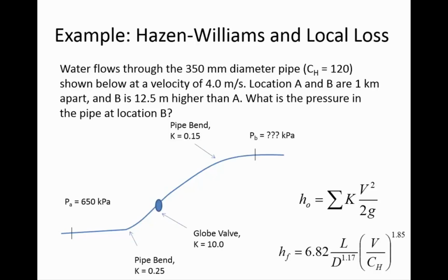All right, first of all, does anybody remember what that bar above V1 and V2 means? It's implied when we usually use it, but what is it? Average velocity, right. Because remember that in a pipe, there's a whole range of velocities. At the center of the pipe, the water is moving more quickly than at the edge of the pipe. And so usually we don't bother to put that bar over the top of it, but it's implied. What we mean is the average velocity. I just wanted to re-emphasize that. What about the alpha that's in front of the velocity head term?